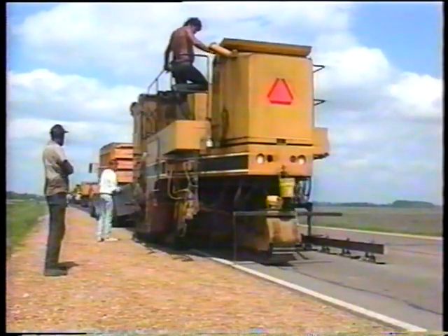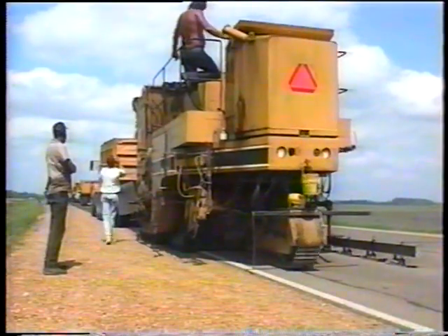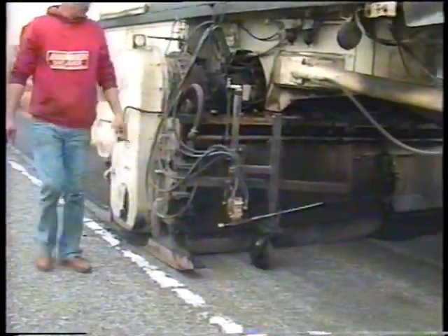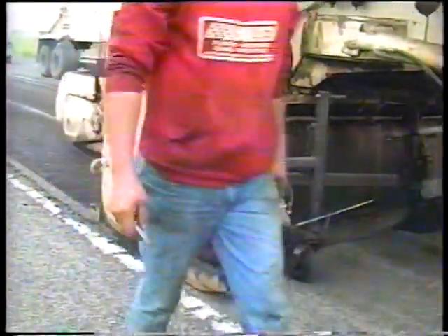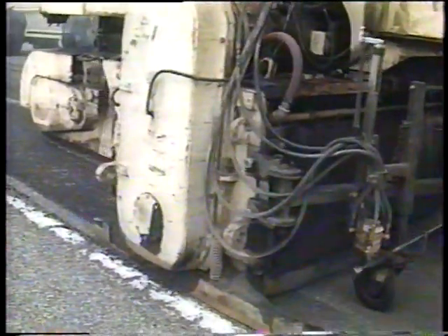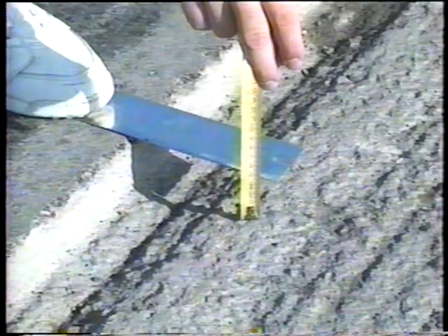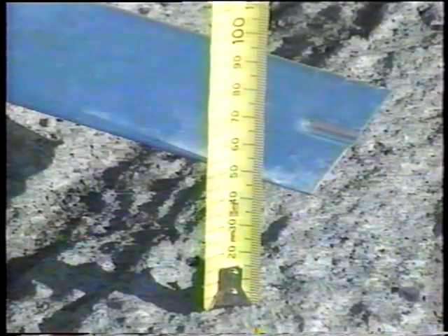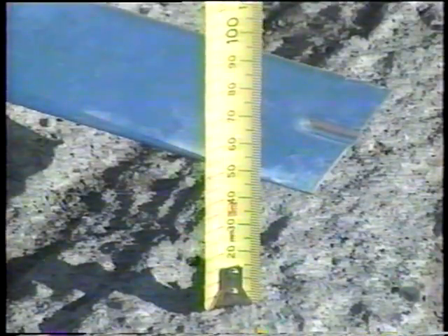Along with pothole repair and pre-leveling, many projects specify milling. Milling is often used in urban areas so that the new pavement will match up with existing manholes and curbs. This procedure is also effective in eliminating wheel ruts. When milling is required, your first major concern is that the pavement is milled to the proper depth. Also, be sure that the milling equipment does not tear or rip the surface.